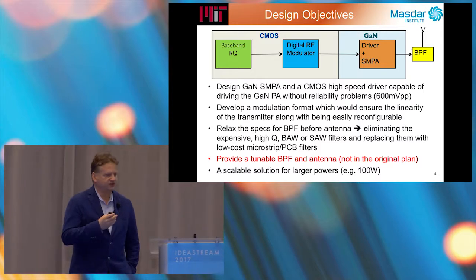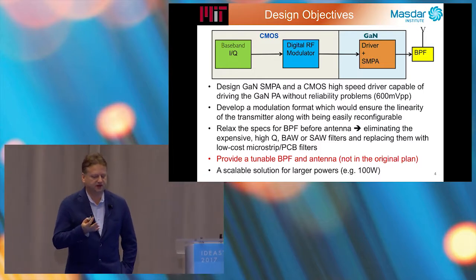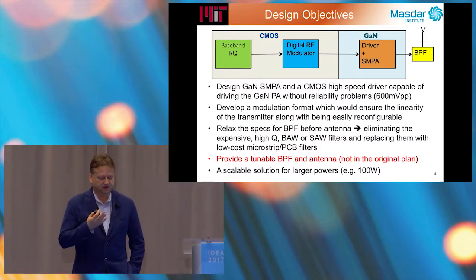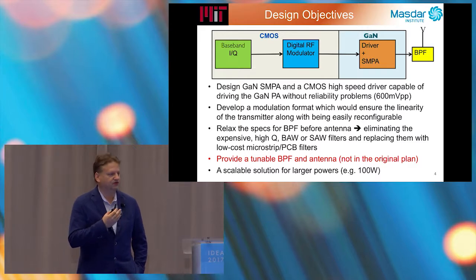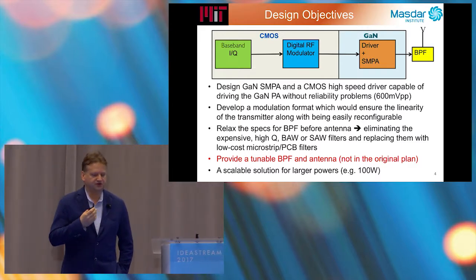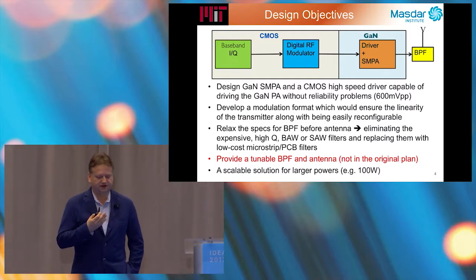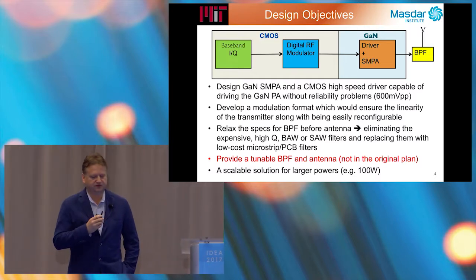So these are the design objectives. We want to build gallium nitride switch mode PAs, very efficient, with a CMOS high-speed driver capable of driving this gallium nitride chip without reliability problems. We want to develop a modulation format which will ensure the linearity and is easily reconfigurable.